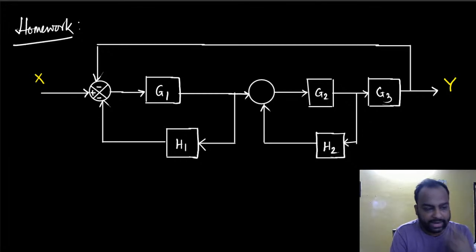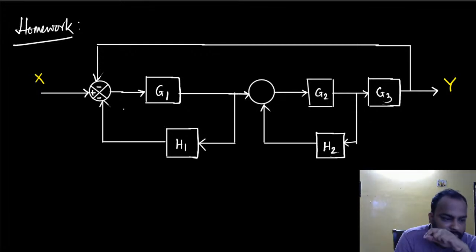So again, just look very carefully. It's kind of a comparator, but two feedbacks are going into this one. So of course you have to put a plus sign here when you are doing the signal flow graph technique. So here that's going to be a +1 and put a minus sign here. This is going to be a +1 and put a -1 here, and subsequently like that. That's going to be plus, that's going to be minus, and just like that.